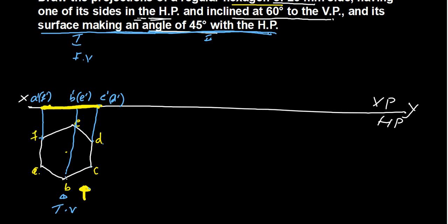Okay, so now whatever the distance of this A to D is, take the same, and draw a 45 degree angle inclination line. Measure this distance from A to D, or you can say A to C or A to D also. Whatever distance you have, measure from here to here and mark it on this line. Now this becomes your distance.